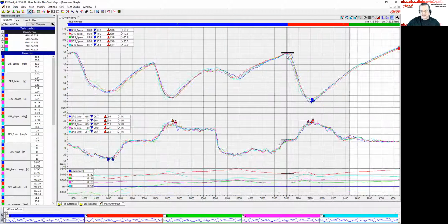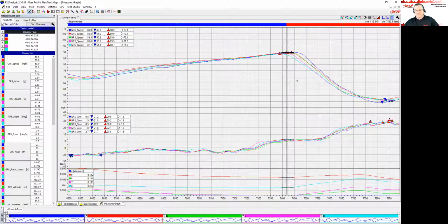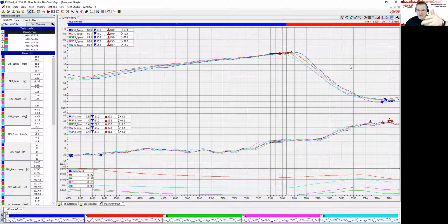Oh, this is a good one. Let's look at this one. This one I screwed up on. You see this? The blue segment is where I ended it. The lap I had looked at was only the fastest lap, which was the blue one. I assumed that we were always on the brakes, but look at this. Several other laps, I'm actually hitting the brakes earlier than the segment as I did it. So what I would do is come back here, put the cursor back where I know I'm still on the throttle, and that is at 73.72, right? So maybe we adjust that track map at some point. But it's another great way of checking and making sure your splits are falling where they belong.